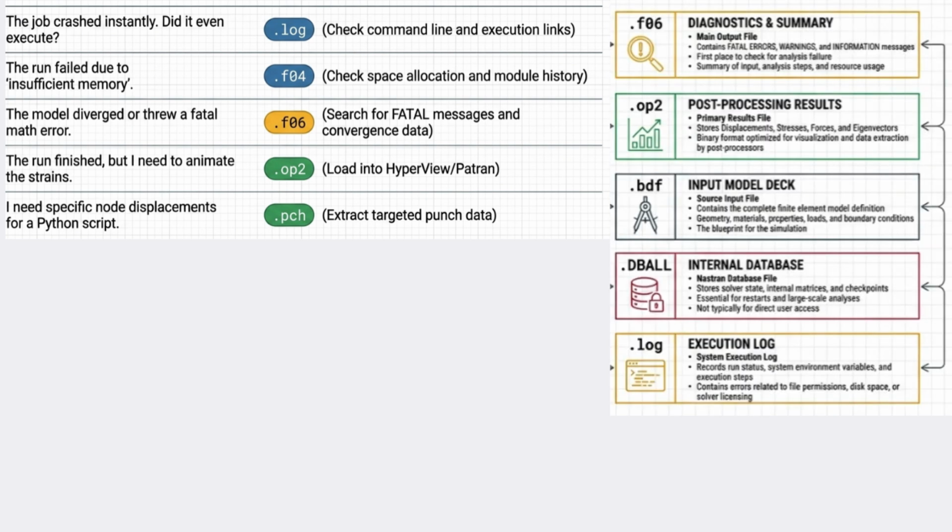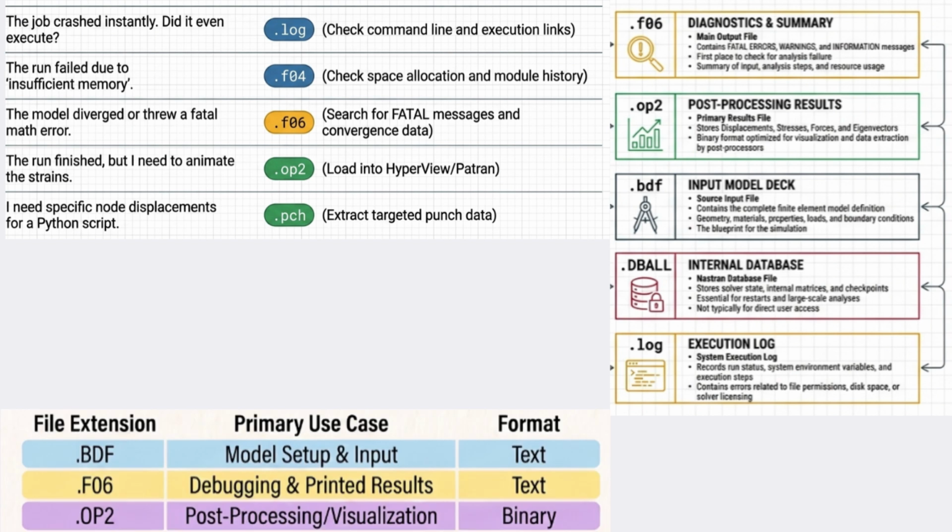So, understanding these files is important because when a Nastran analysis fails, you should not just look at the error message. Knowing which file contains which information can make debugging your model much faster.